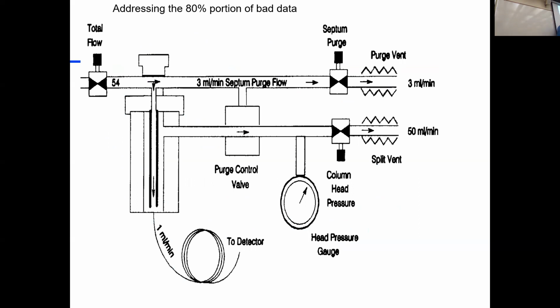And so our problems are most commonly in this section of the gas chromatograph. There's a septum up on top. That's a polymer septum. Again, you're piercing that with a syringe. If you don't replace that fairly often, guess what? You're going to have a hole up there. And guess where your flow is going to go? Your flow is going to come in and go that way. That doesn't help you with separation. So one choice, replace that septum.